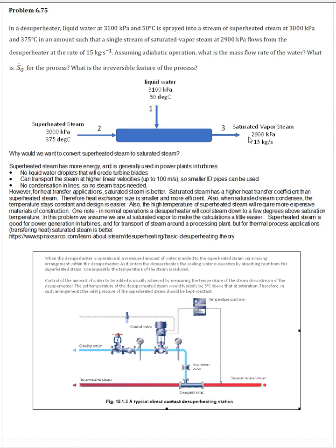The other thing that I wanted to note is that in this problem we are specifying a saturated vapor stream of steam coming out. The reason we are doing that is simply for ease of calculations, because we are using the steam tables. In reality, you aren't going to be right at the saturation conditions. You're probably going to be 2, 3, 4 degrees above saturation, several degrees of superheat, and that's just for practical purposes, so that you aren't dealing with condensation where you don't want it to happen.